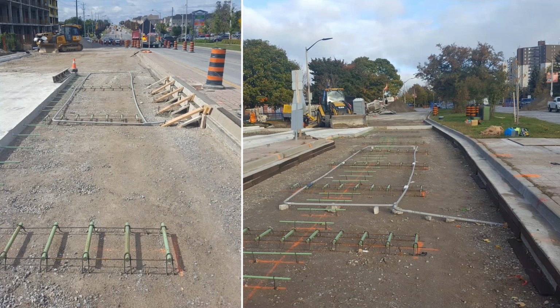So the traffic loops, again, we wanted preformed loops so that they weren't cut into our brand new concrete. There was some concern that because the loops were sitting on and around the dowel bars, the load transfer devices here, the steel would continually trigger the loop, like the left turn signal, for example. But this isn't the case because the loops are calibrated after installation and they're triggered by the net change in the electromagnetic field when a vehicle passes over top.